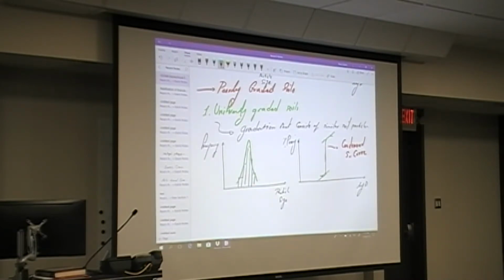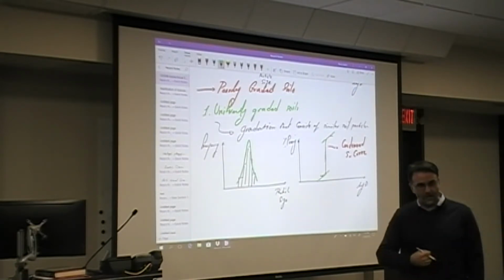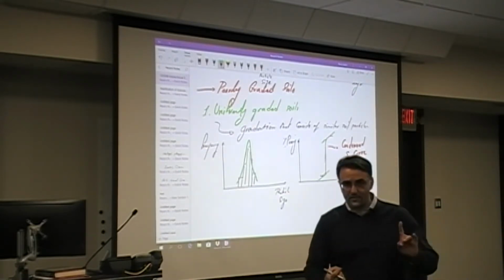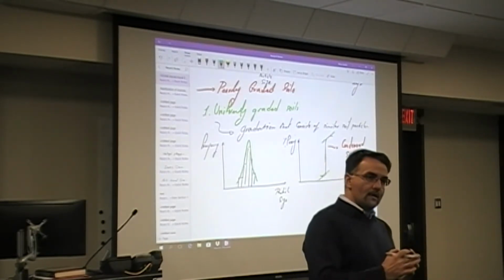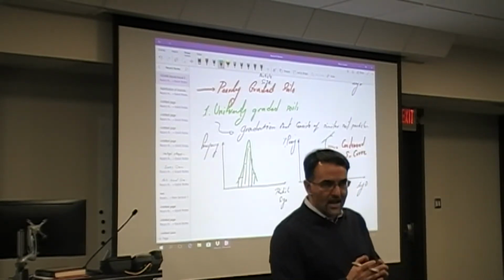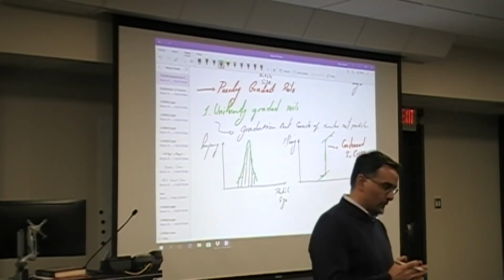Omar, what can you tell me in terms of the permeability of that soil? It's good. We are looking at uniform gradation here. We don't have small particle sizes and intermediate particle sizes. You just have one particle size in there, for example, ideally. And there are going to be big, huge gaps in between the particles, right?